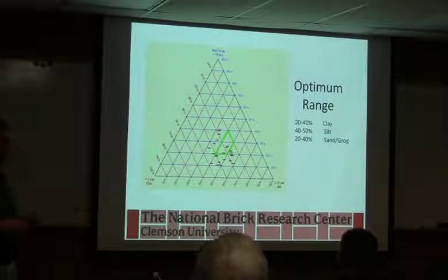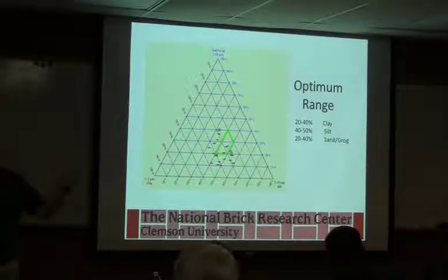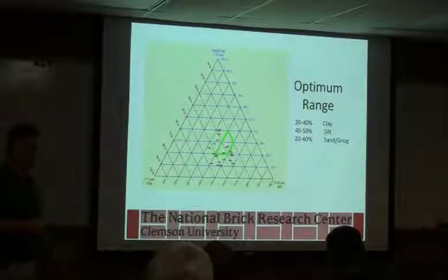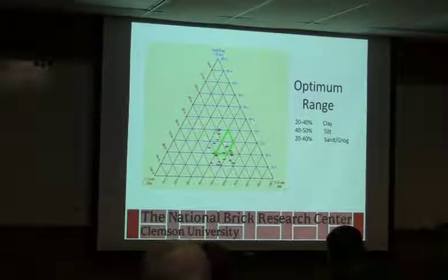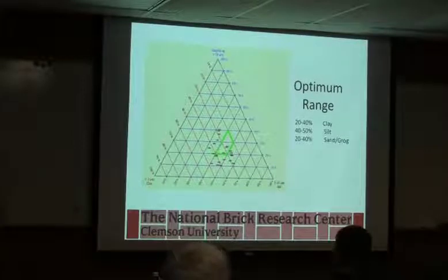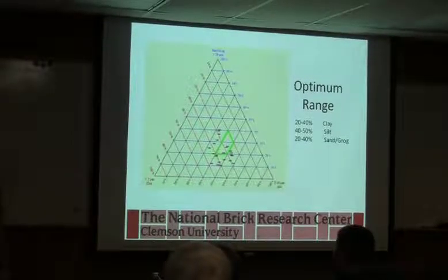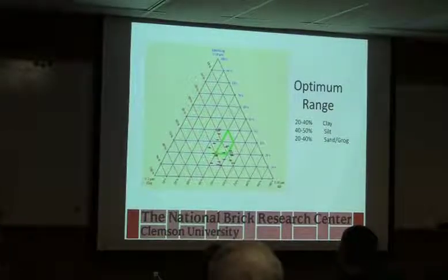And when you build that going forward and you're taking your data in on the particle size as you're running regular production, you haven't had a problem yet, but all of a sudden you've now drifted over to here. You know that you're going to need to watch and make sure, because otherwise I've got 10 or 33 cars in the kiln, and the first one just came out and there's a major issue, and now I'm in for a world of hurt because I also have my dryer full and everything else full.